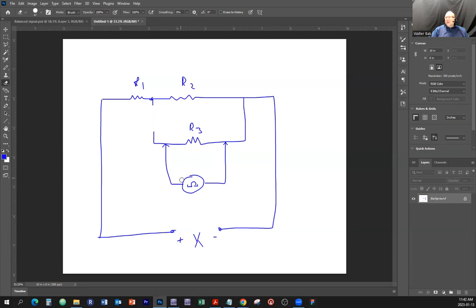So remember, the ohm meter introduces a tiny bit of voltage to pass through that component in order to create a current flow, and its internal circuitry is going to measure the current, and based on that, it's going to calculate the resistance of whatever is connected. So the current flow will go from here to here. That's it.